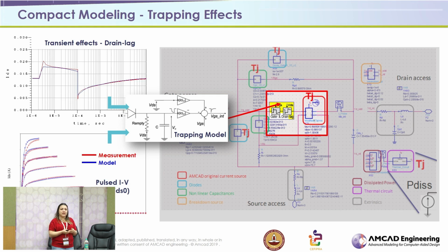After we have done this kind of extraction and optimization, we will also use IV characteristics from another quiescent bias. Here the example is done for VP and a certain VDS0, in class AB typically. And you will shape and tune some parameters to reproduce the shape of this network. We can do this job for different quiescent bias, so class AB, class C, it depends on the needs.